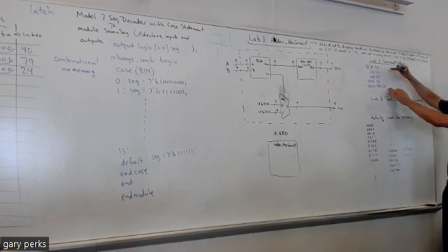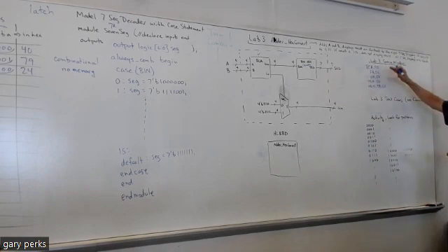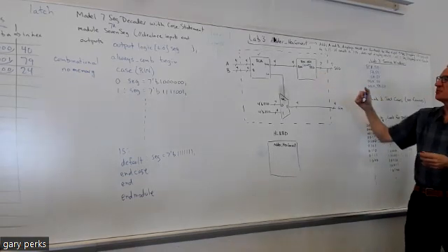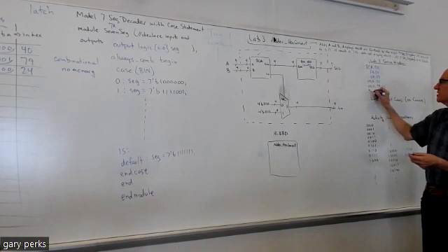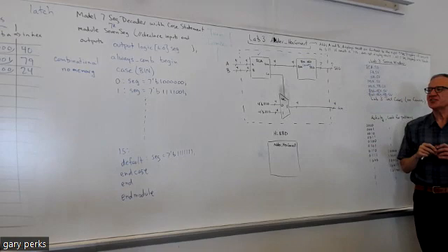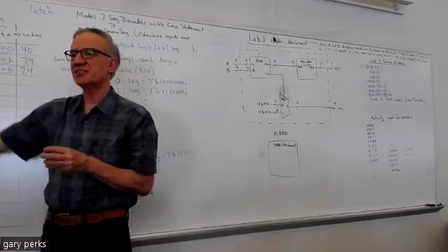Okay, so if you're not at this point, you start with the MUX. But if you have all of this, then where you start today is you want to do a design source for this decoder. You can call it bin_x, or you can call it decoder, whatever you want. And you'll need a SIM file for this also. How many test cases are you going to need for the decoder? 16, right? You want to show that your decoder gives this truth table.